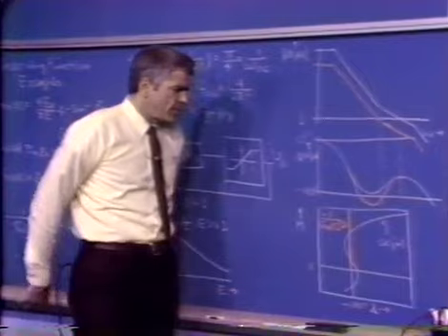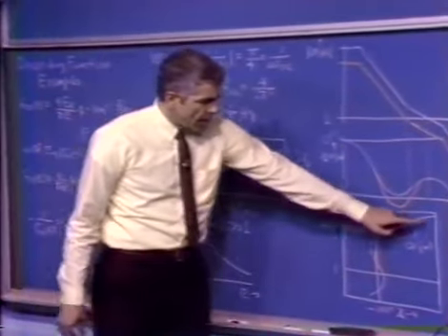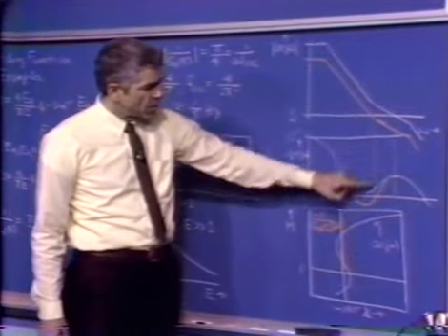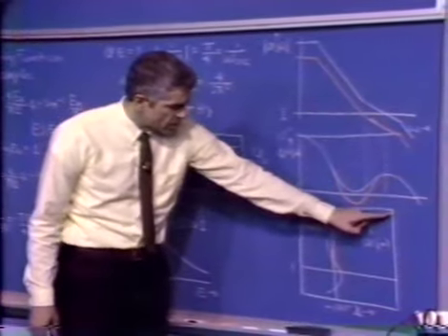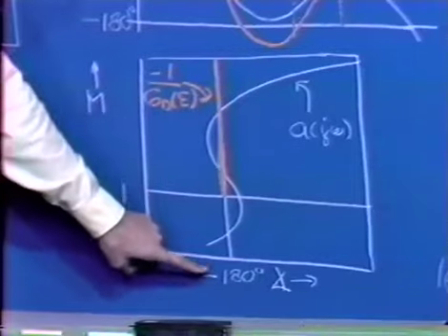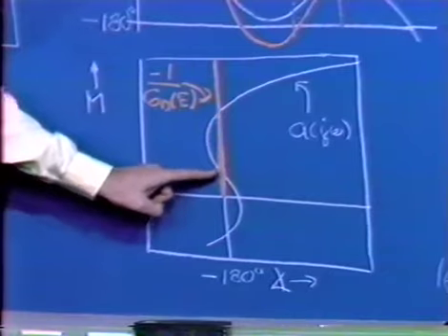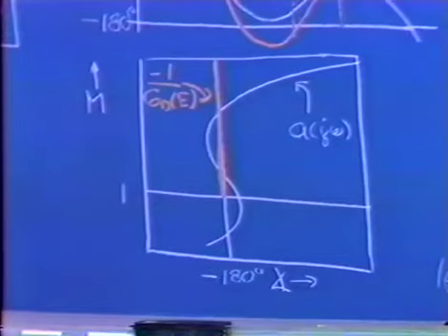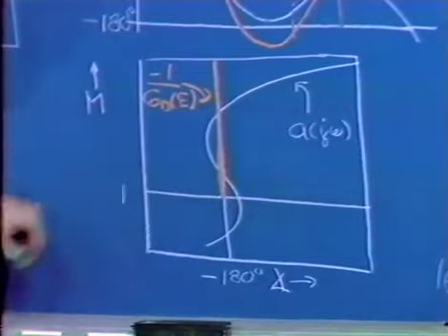We can look at the same thing in a gain phase plane, do our conventional describing function analysis. The same kind of curves, this sort of a magnitude curve combined with this kind of a phase curve in gain phase coordinates, of course, starts out, the magnitude is always decreasing, the phase goes down more negative than minus 180 degrees over a range of frequencies, omega is a parameter along the curve, eventually recovers to values more positive than minus 180 degrees. Hopefully that occurs in the vicinity of the unity gain frequency so that we have a system that has positive phase margin.